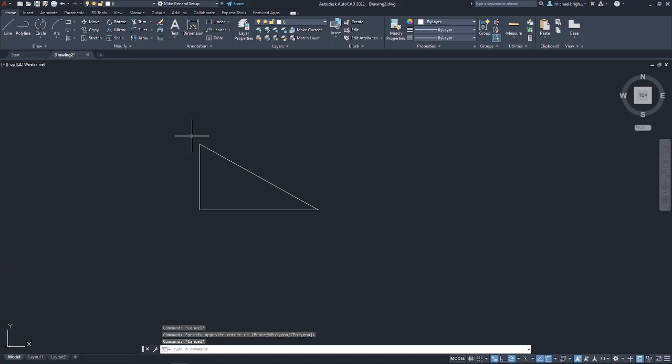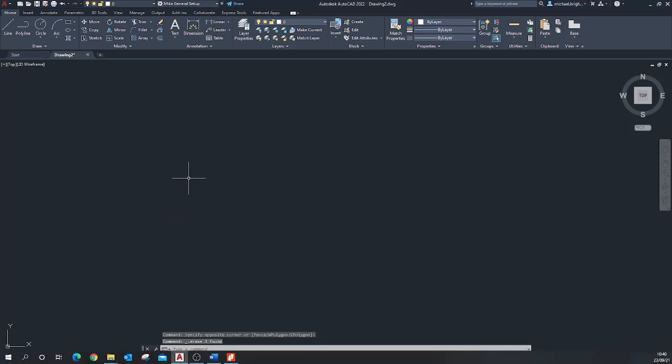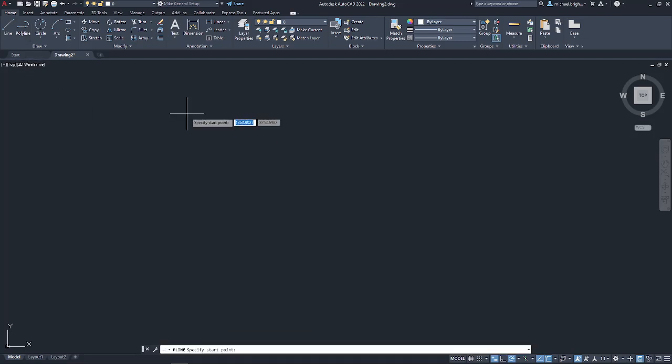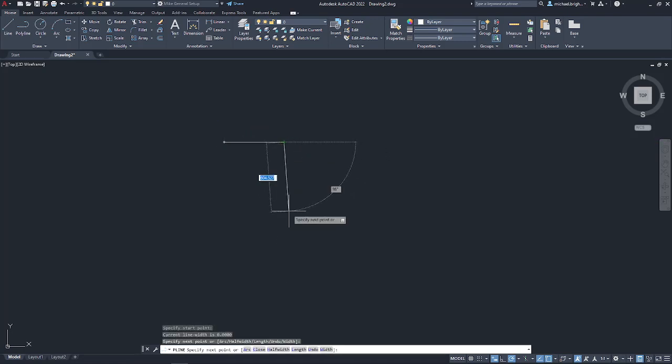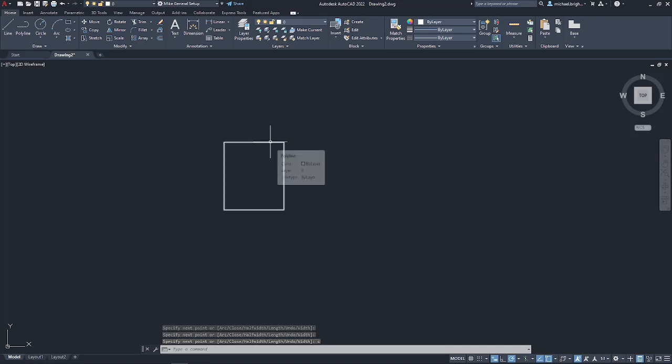So moving on from lines, obviously we know how to draw lines, delete. Polylines. Now a polyline is a joined line, it's a group of lines. Polylines are quite useful if you want to draw shapes, if you want to draw a single shape. A polyline works exactly the same way as a line, however with a polyline you can create a square. So you get the 3 points. If I drag it up a little bit and click C, enter, it'll close my object and it'll create an object. So this has created an object rather than just a group of lines.